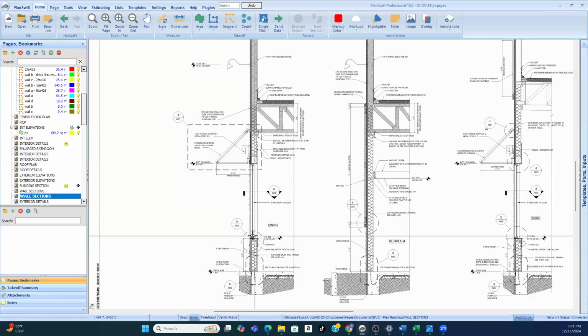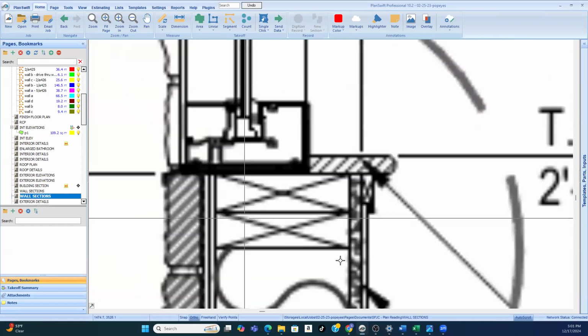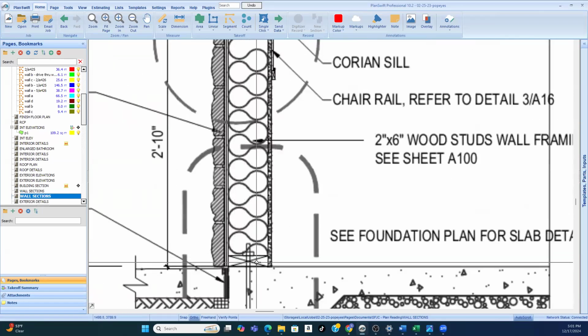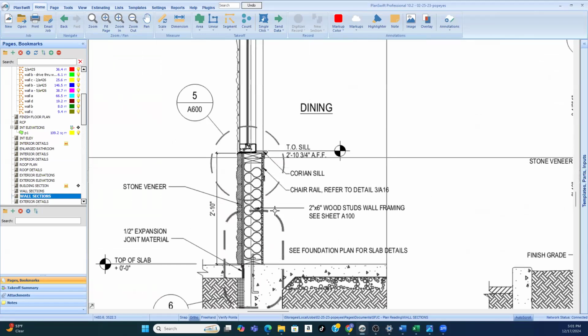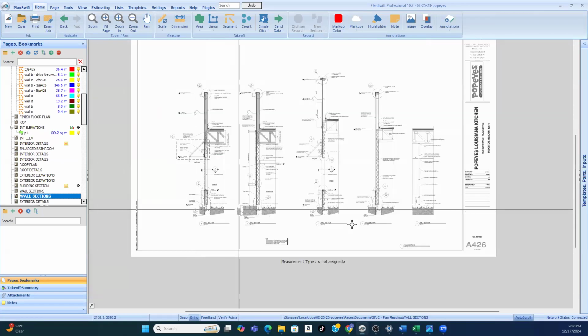So the framer knows the length of the wall under the window, and knows that X's mean two-bys, 2x4s, no metal. Anytime you see the X, it's a 2x4, 2x6, 2 by something, wood framing. And so I know I have one bottom plate, two top plates, and then however many linear feet. So that's the job of the section view.